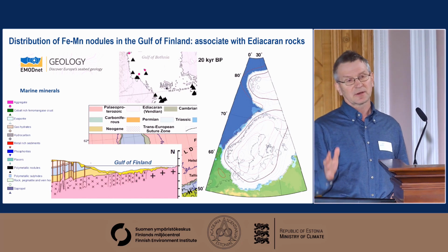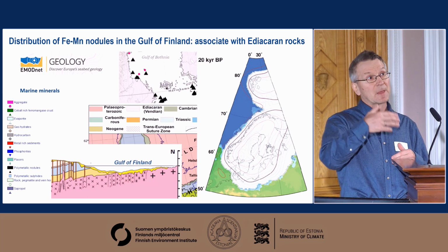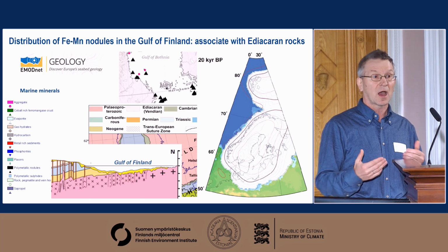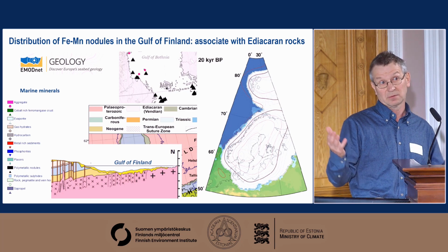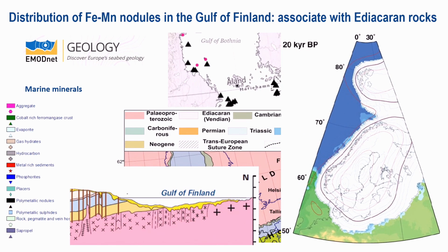it's kind of interesting, but if we also consider the more recent geological history during the glacial times and deglaciation, then when we had the ice at its maximum 25,000 years ago, we had 1,500 meters of ice on top of whatever substrate was here, and this generated quite some extra loading for the underlying strata and could generate in these aquifers extra pressures which were released when the ice was taken away.